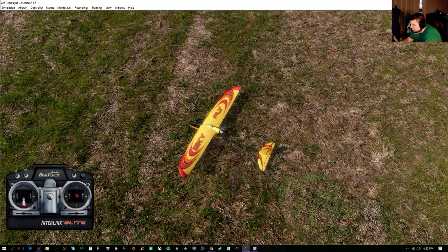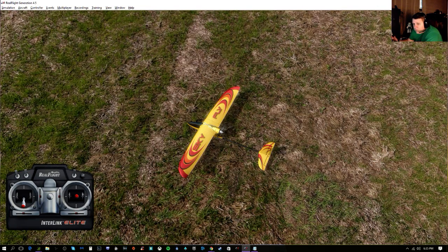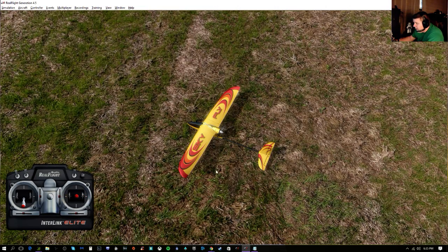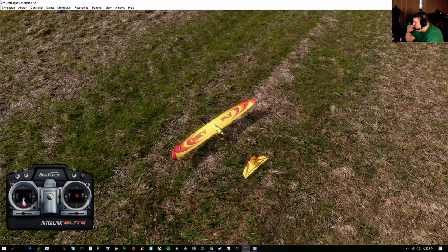When you use your rudder, which is the left stick right here, you're going to see me moving it down there. That right there does absolutely nothing on a 3-channel airplane. Okay, so with the right stick, which typically is your aileron, your ailerons are typically cut out right here, and there are 2 servos that work that. That's not there. Where you're seeing that in this plane is back here at the back where your rudder is. It's tied to your aileron channel.